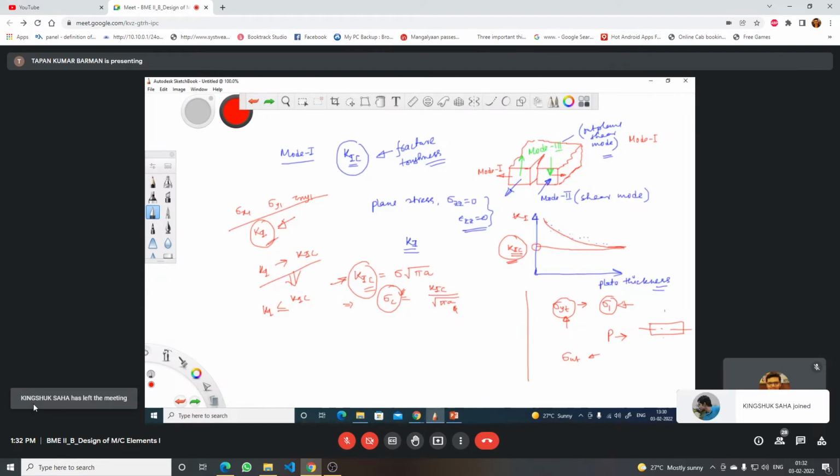Now it is okay, sir. Okay, now here also what we will do, we will try to calculate the stress intensity factor. We will get the value of K1 and we will compare that thing with K1C, and from there we will try to get the design, or we can make the design of this material. So we have another separate chapter on this. Right now, basically what is material property, for that purpose only we have defined this thing.